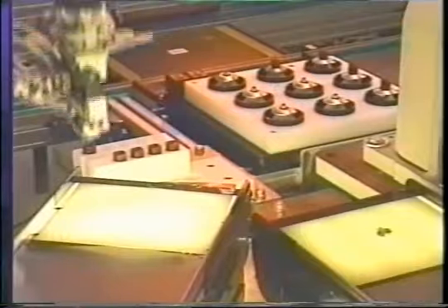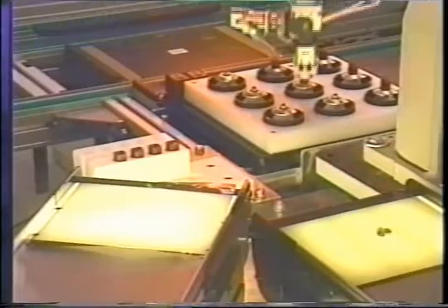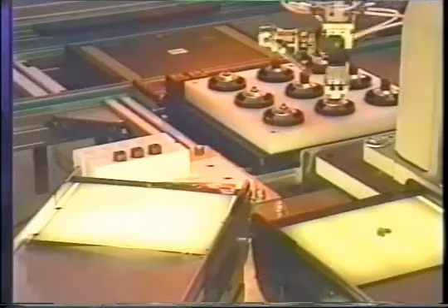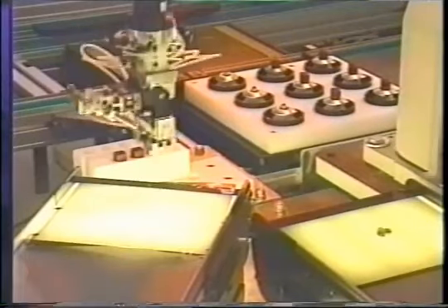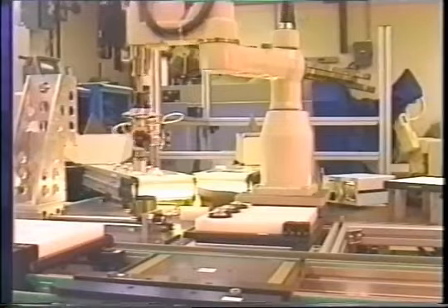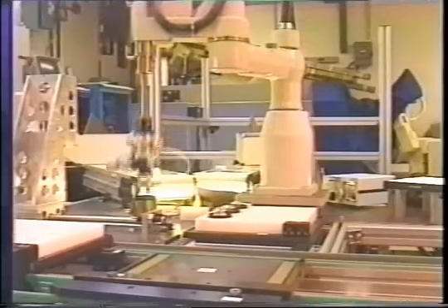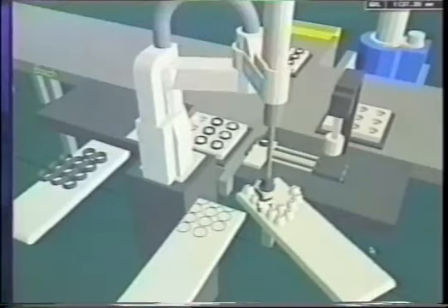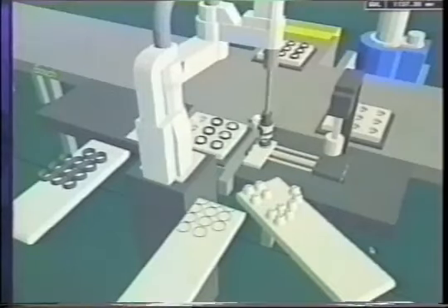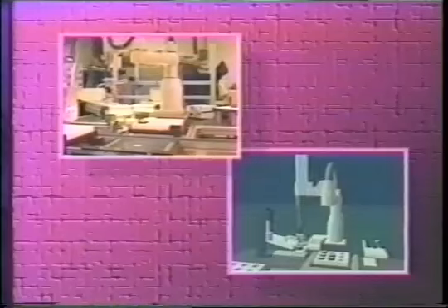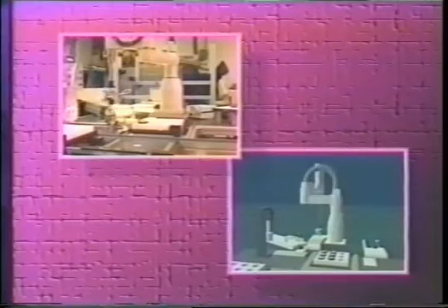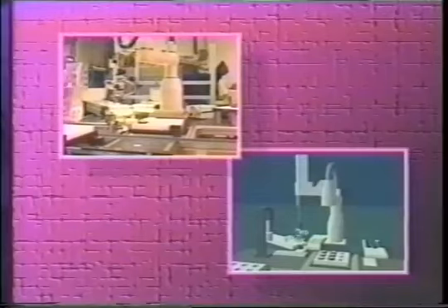The relatively primitive Adept robot controller has been augmented by an innovative control system. This allows the use of object-oriented programming and advanced programming tools, which in turn permit software to be modified quickly and efficiently. To expedite software maintenance, a graphical work cell simulation was developed. Control programs can be tested on this virtual work cell where software errors can be safely detected. This facilitates changeover by reducing work cell downtime and the risk of equipment damage.